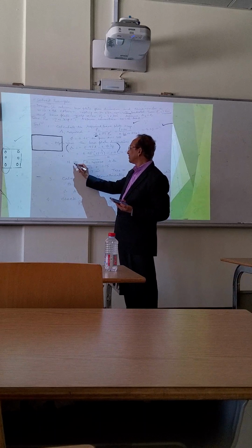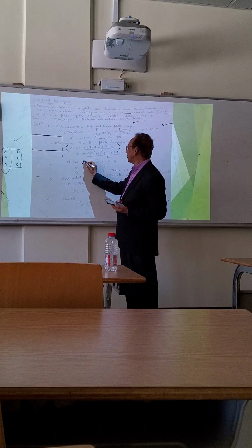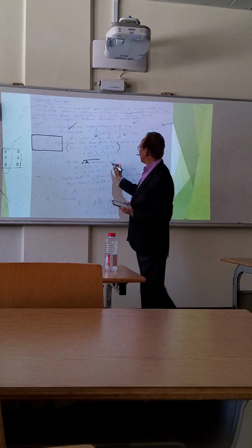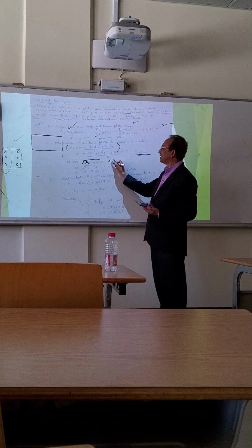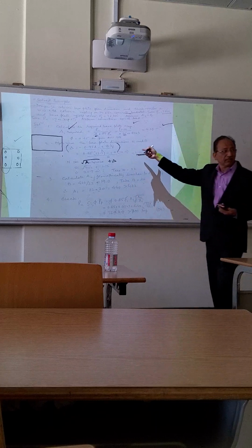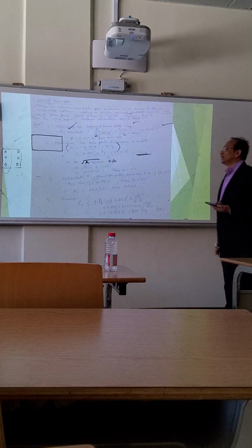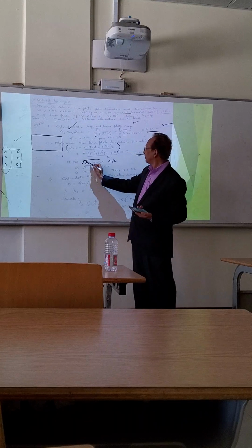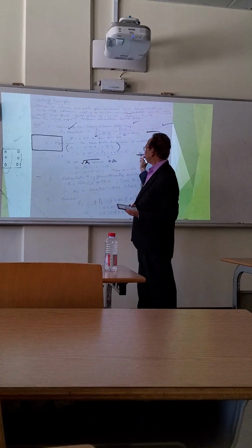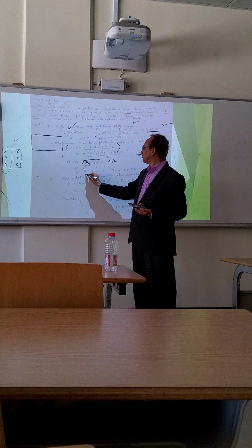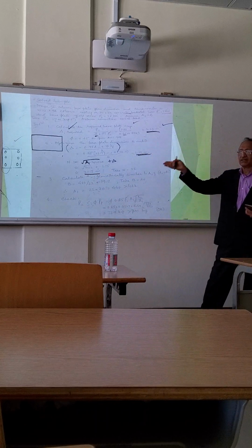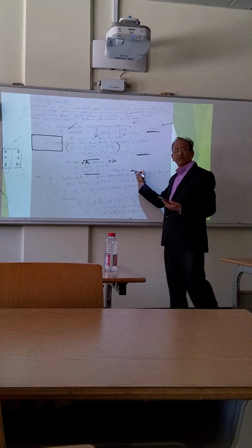So N is approximately equal to the square root of A1 plus delta, which is the square root of 422 plus 1.15, so it comes out to be 21.7. We will not take 21.7; we round up to the next number, so it is 22.